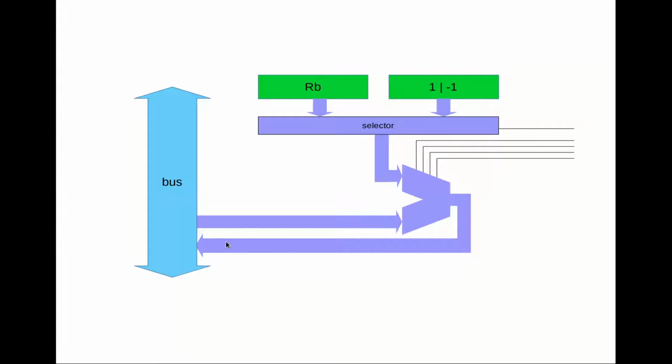So we can't do that, in the same way that we couldn't do it for registers. So at the very minimum, we're going to need to buffer the output back onto the bus from the ALU. This could be one of these 74HCT245 chips, for example, which we've been using in the rest of our computer, which is going to allow the control unit to decide when we're going to output on the bus. And so it can then make sure that if at any point the ALU is outputting onto the bus, then none of the other registers should be outputting onto the bus.